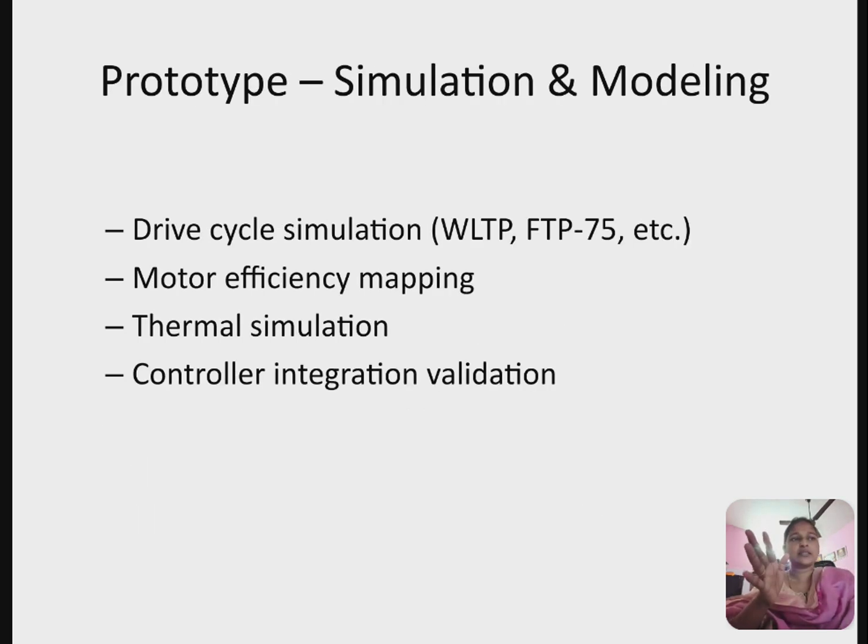Once we select the motor based on the available options, we move to the prototype stage. Here we don't directly build the motor, we first test it using simulations like drive cycle simulations, in which we pose real driving conditions, and efficiency mapping, then thermal simulations like heat analysis, and also we will be testing controllers to make controller integration validations. This helps us avoid mistakes before the actual production.